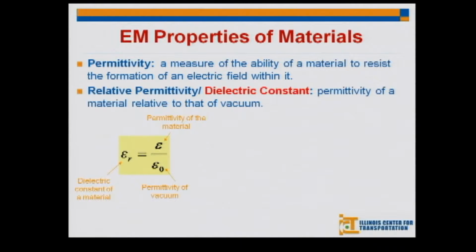Please notice that I will be talking about the dielectric constant as an absolute value, but I wanted to emphasize that the dielectric constant is a complex number which has two parts. The real part has to do with the storage, and the other part, the imaginary part, has to do with the loss. An example of that is if you are using the microwave at home, you take the food and put it in the microwave. If you have your food completely dry, you will find that it's going to take a long time to heat it. But if it has a little water in it, because water is a very lossy material, the food will be heated much faster.